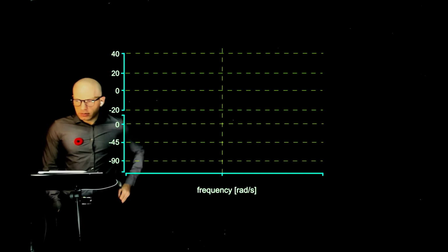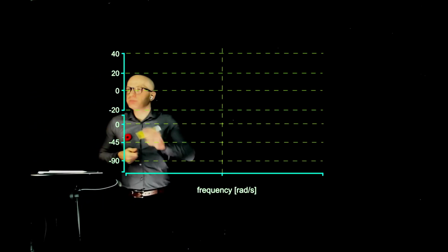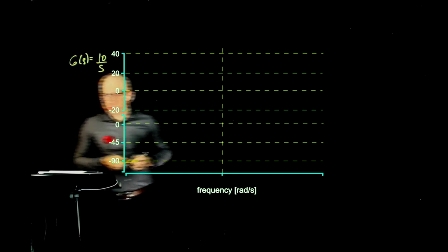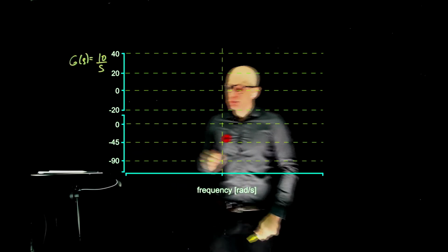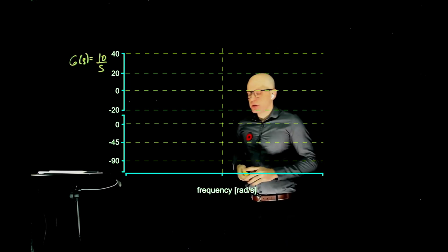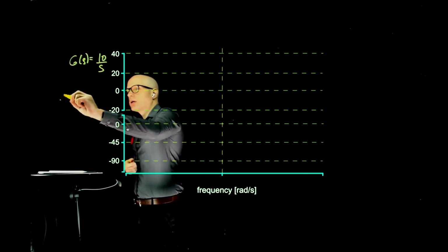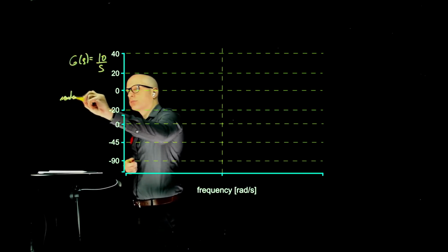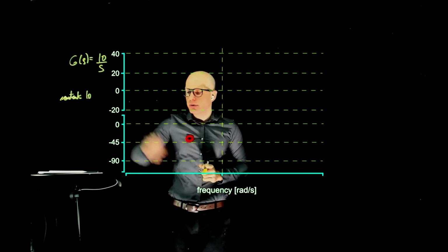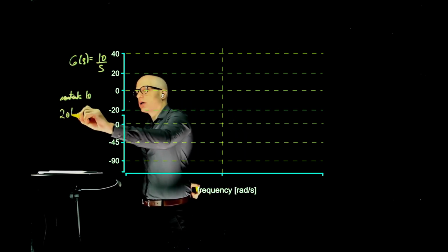Very well. So here is the Bode plot, with function g of s equals 10 over s. So we saw that because they have two building blocks, we can do the Bode plot for each of them and then simply add them up. So let's start with the constant gain, constant 10. What happens to the constant 10 in the Bode plot? Oh, we are doing that in decibels, don't forget. So you're taking 20 log of 10.